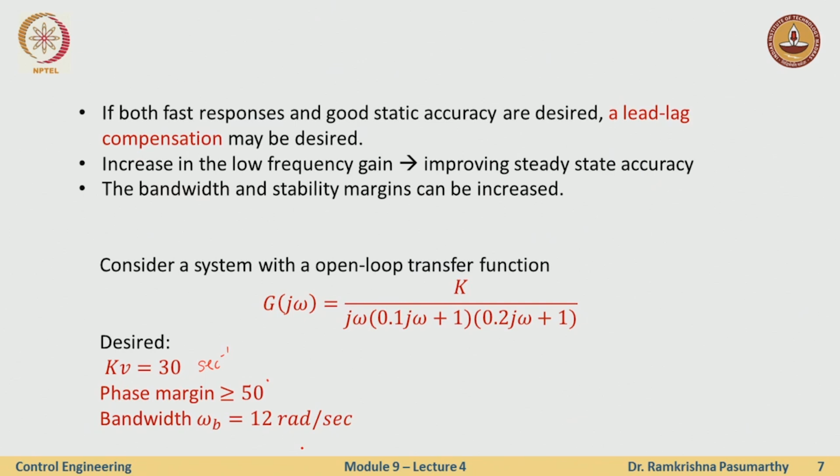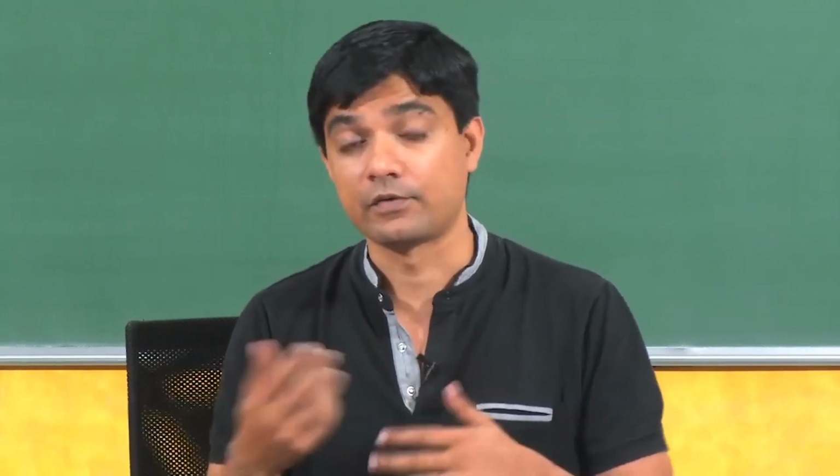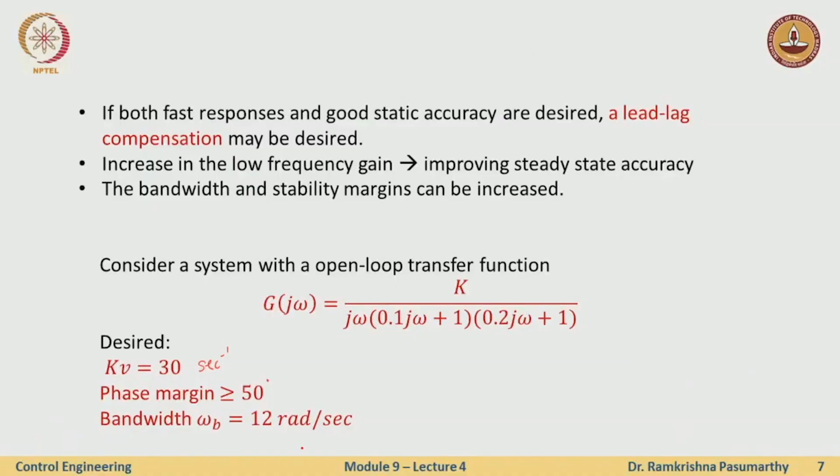Many times while designing, I had mentioned that the design is not a one-step process. You may have to do it over and over until you get closer to the solution. So in the first iteration you may be close to the desired results, but not quite. Then maybe in the second iteration you may tune your parameters, which are essentially the beta. Maybe you can choose a different alpha and beta, as we did in the time domain analysis, to tweak it a little bit so that you get the desired response. So I'll quickly run you through that process.